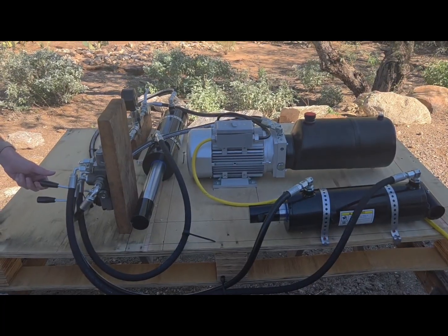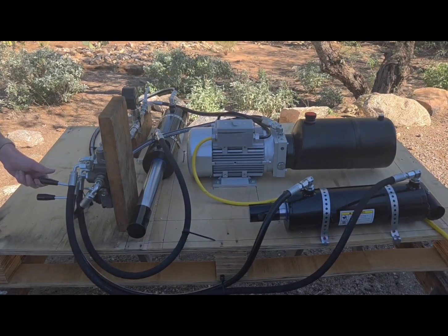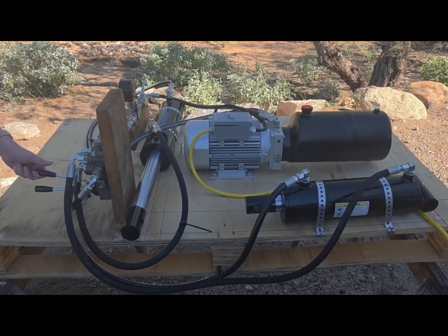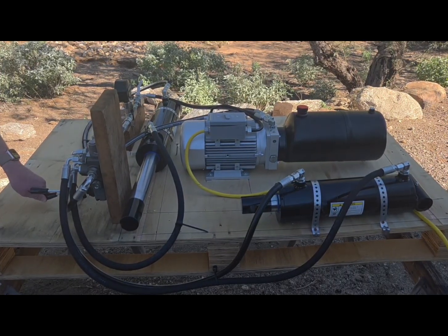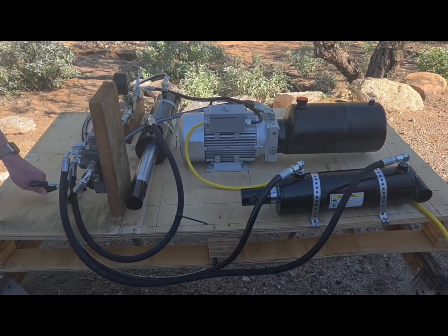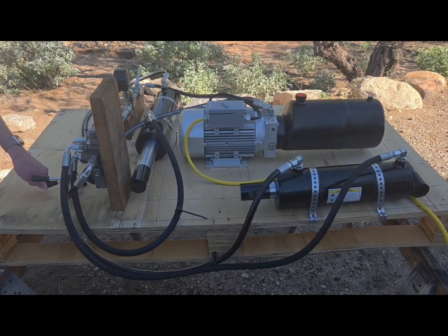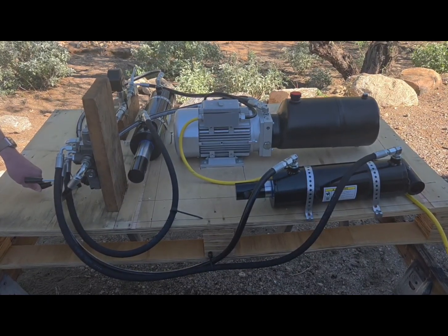In addition to the cylinders, the compression chamber is specifically sized to produce consistent bale dimensions, which helps with repeatability. We also included a hopper system with a vibration motor to help the material settle before compression, and an ejection system that allows the bale to be removed cleanly after it's formed. All these components work together to make sure the system is not only effective, but also consistent and repeatable in its performance.